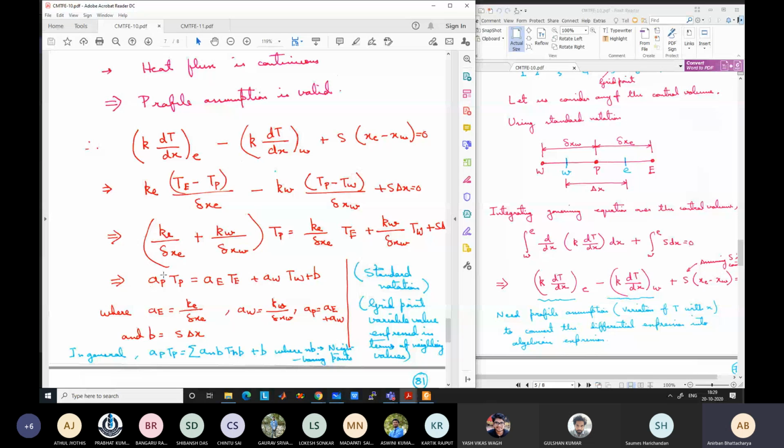You can ask how we know conductivity and geometrical parameters. So conductivity we will see today, how to calculate at the interface. But remember, we know the material properties, so at least we know the conductivity at each grid point. Based on those conductivities, we need to find some equivalent conductivity at the interface. But for each grid point, the conductivity is already given as an initial input to your problem, because you are assuming that, say, this is aluminum or something like steel, or say up to P, this is aluminum, from P, accordingly conductivity also can change.